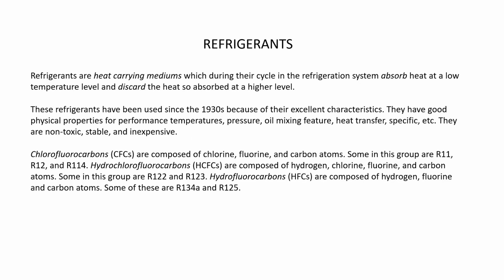So now, what are the refrigerants I can use for it? Refrigerants are the heat carrying medium which, during their cycle in the refrigeration system, absorb heat at a lower temperature level and discard the same amount of heat which is absorbed at a higher level.